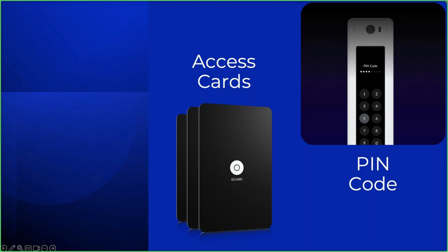And as an alternative to that, if they don't want to use access cards, you can also set up PIN codes. So you can say, for example, that if someone's only going to have access to this building for, I don't know, a week or something like that, you can set up a PIN code to say, okay, cool, this PIN code is valid for 7 days, and that PIN code is associated to a specific employee or group of employees if you prefer.